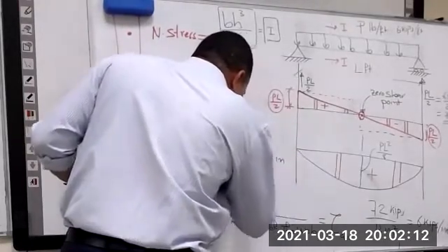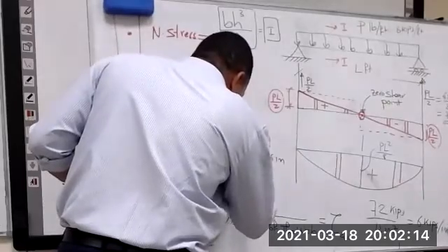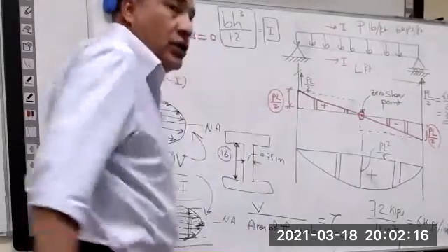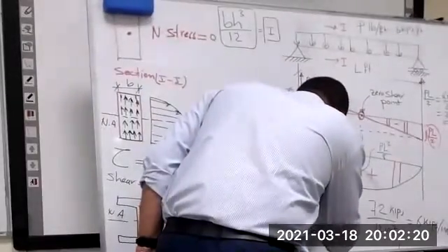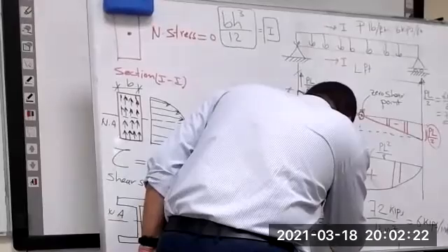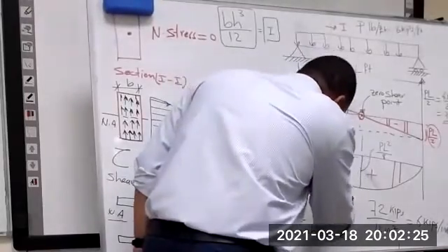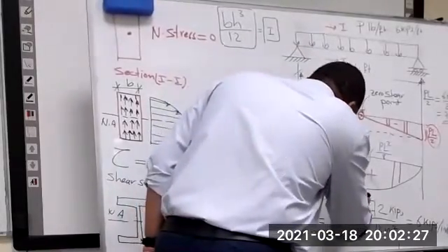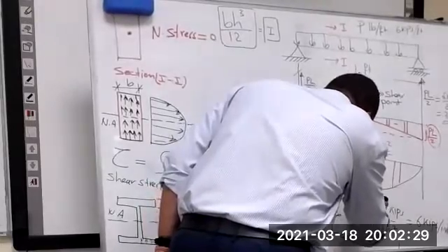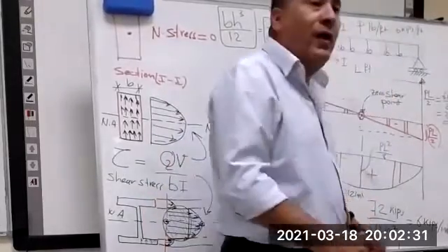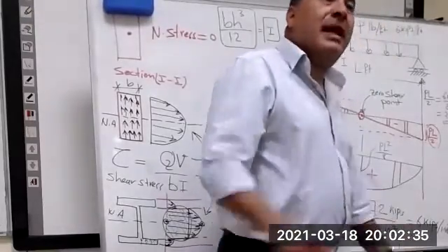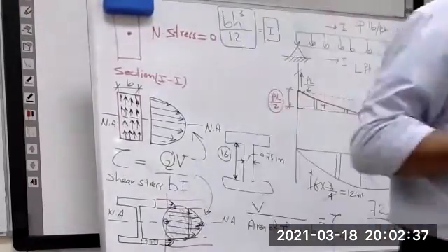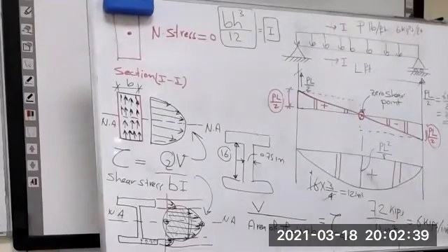And here is 16. Area is 16 inch multiplied by 16 multiplied by 3 over 4, equal 12 inch square. So 72 over 12 inch square equal 6. That is the average. 6 kips over what? Don't stop. Over inch square.